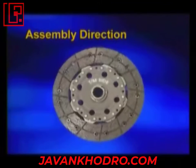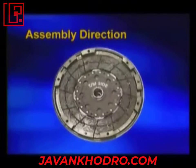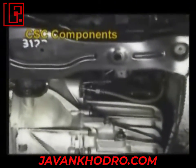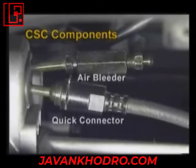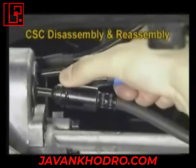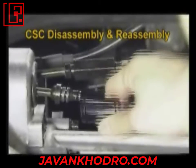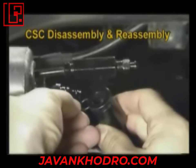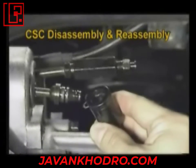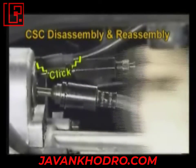Since the clutch disc has direction, assemble it by the distinguishing marks on the disc surface to the engine side and the transaxle side while replacing CSC hydraulic line, which consists of a hydraulic hose connection and air bleeding. To remove the CSC and hydraulic hose, pull the quick connector of the hydraulic hose after removing the clip. To assemble the clip to the hydraulic hose and push the quick connector in, and then assembly is complete if a clicking sound is heard.